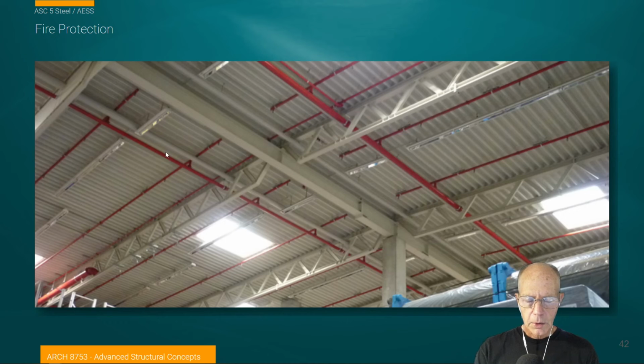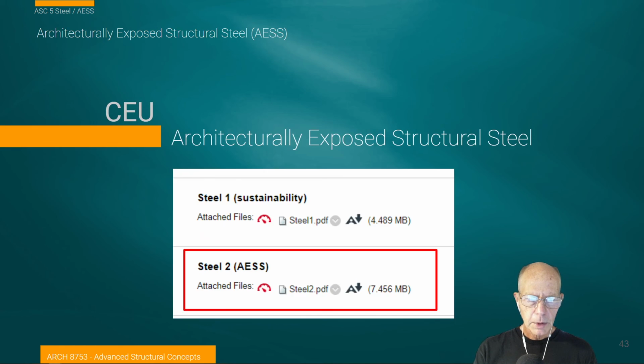And then the other way that we can deal with the idea of fire hazard and heat destroying the structural properties of our steel is the introduction of sprinkler systems. And this may come along as a requirement, regardless of the construction type, just as a code requirement for the inhabitant and use of the building system. So something to keep in mind.